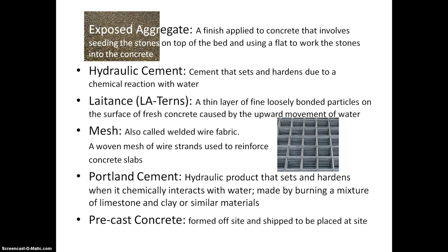Exposed aggregate, a finish applied to concrete that involves seating the stones on top of the bed and using a flat to work the stones into the concrete. Hydraulic cement, cement that sets and hardens due to a chemical reaction with water.